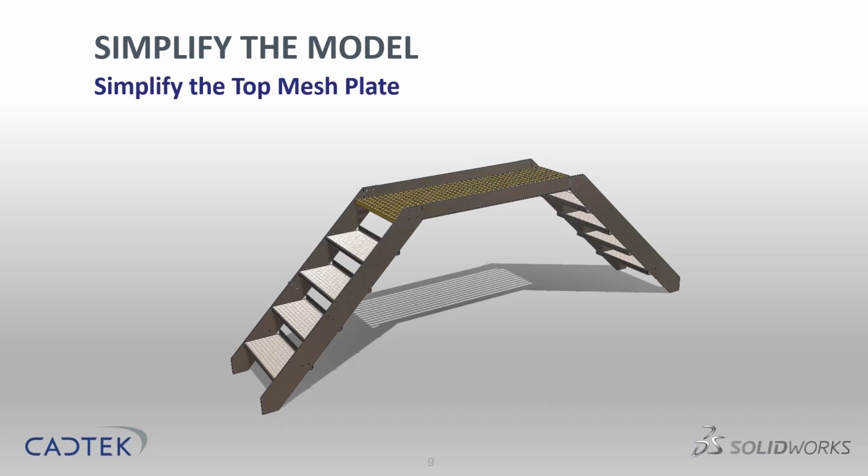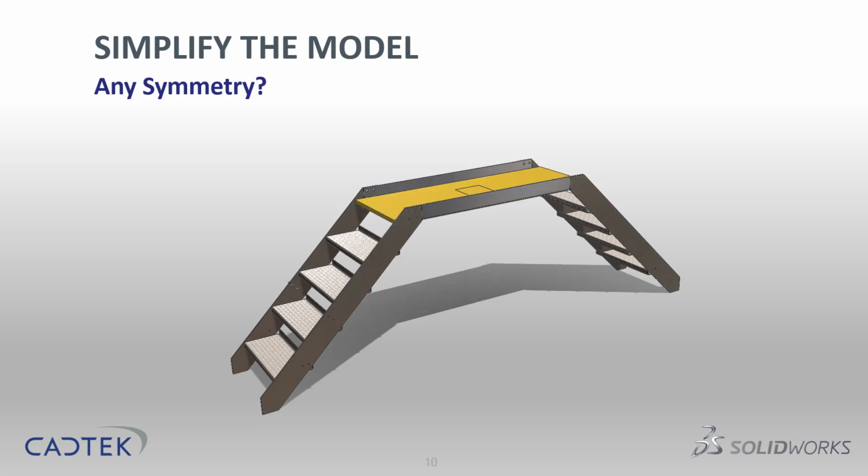The main gantry walkway is from Eurograte. Now that's a kind of a nylon grid structure. Again, if we're going to mesh this up, that's a lot of meshing that's going to be involved, but we have got physical properties off their website that describe how it behaves. So we can simplify our design down, get rid of all the square holes in the part and just use a flat plate.